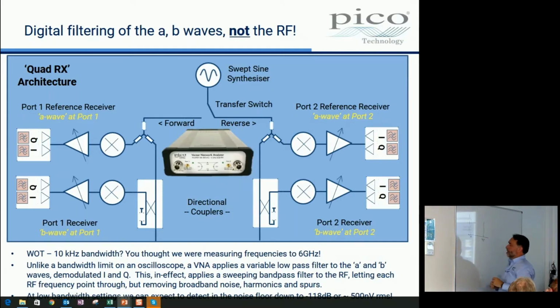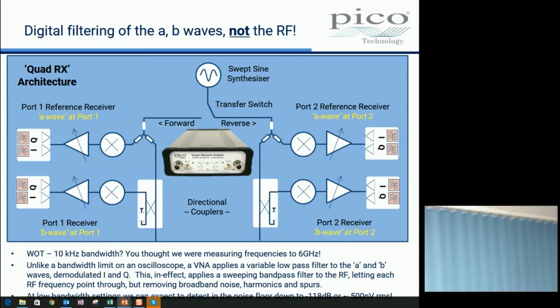So as this 3 gigahertz is sweeping, the other frequency tracks the 3 gigahertz at 1 megahertz behind it, and we mix the two together and we get an intermediate frequency that we are processing through this amplifier. So the signal coming out of here is a 1 megahertz or thereabouts waveform, and its amplitude and its phase information are all connected to the original 3 gigahertz.